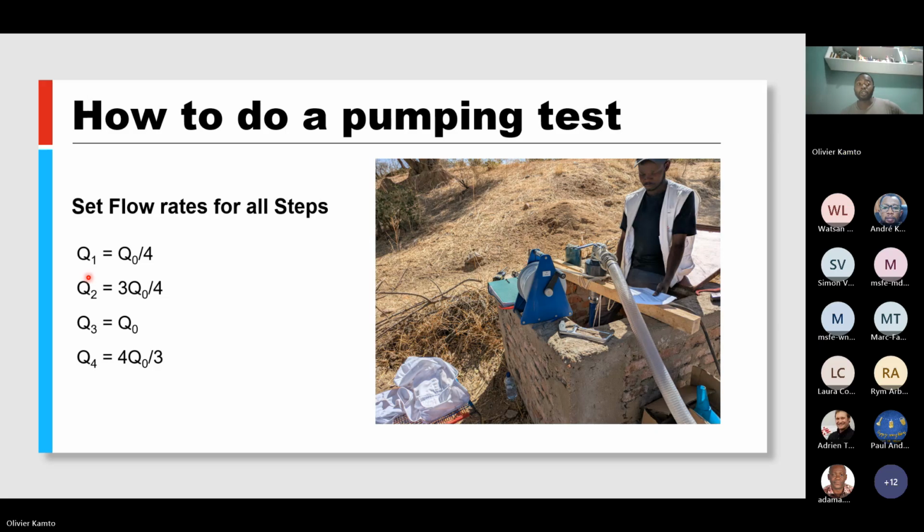We would open the valves based on the calculated Q1, Q2, Q3, and then we try to measure the flow rates, and we set the position indicator so that the next day during the pumping test proper, we are not manipulating the valve very much, because as soon as the pump is started, the only modifications should be to progressively increase the flow rates of the pump. So after having set up Q1, Q2, Q3, Q4, we try to indicate the different positions on the valves